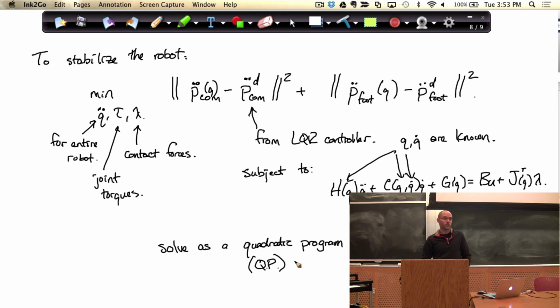And so the LQR control, you can't pre-compute that. You have to know where your current state is, so you have to solve it. I can solve the LQR arbitrarily fast. That's this step, and this step: once I get an LQR control input that I want to do, I have to actually do that. It would be slow to include all these dynamic constraints in it. It would no longer be LQR.